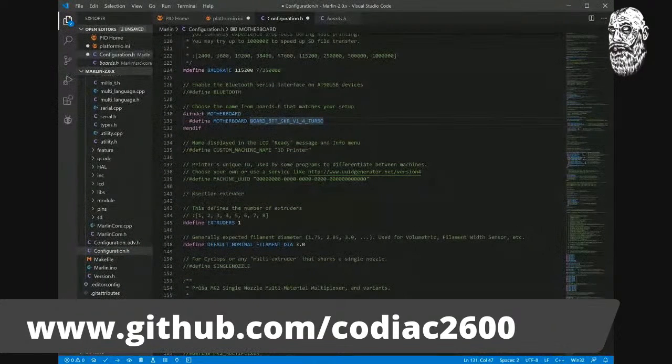Do we want a custom screen name? Yes. We're going to call this printer Slimer. And you can call this thing anything you want. Now remember, the length of your screen determines whether or not you can fit all the text on the screen. So you can write a whole one like, you can write purple monkey chunky, and it might not fit. You might see your screen scrolling. So I tend to pick a shorter name. It's not that hard to change.